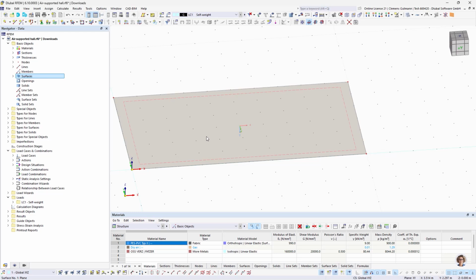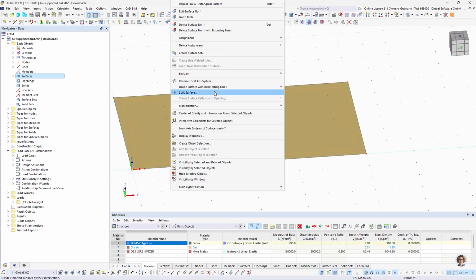So to be able to model this, the surface has to be flat, and then I have the issue that I need to create the volume for the gas, and since the gas cannot be between two surfaces that have zero distance between one another, I have to extrude this a little bit, let's say, into the soil by a little value.